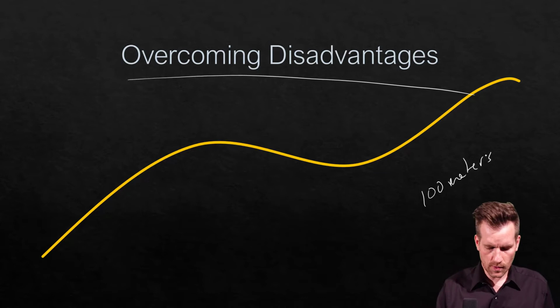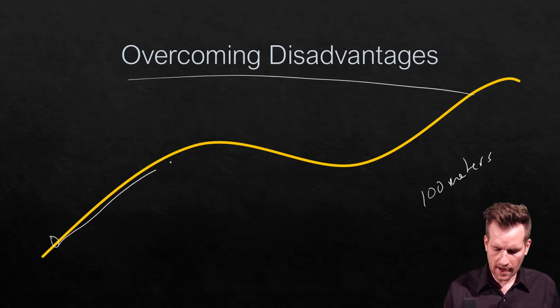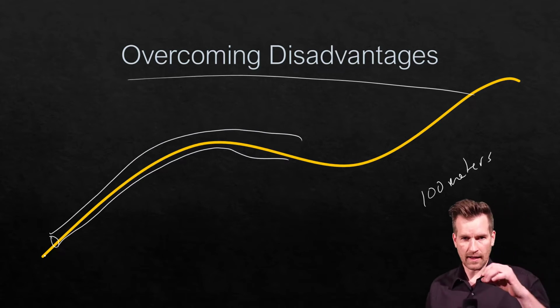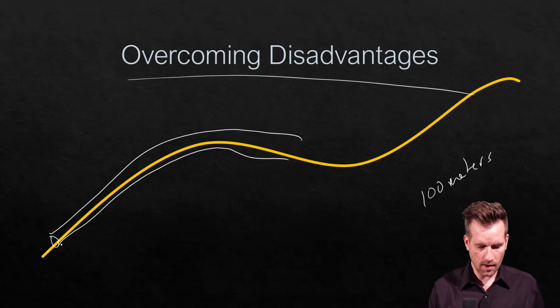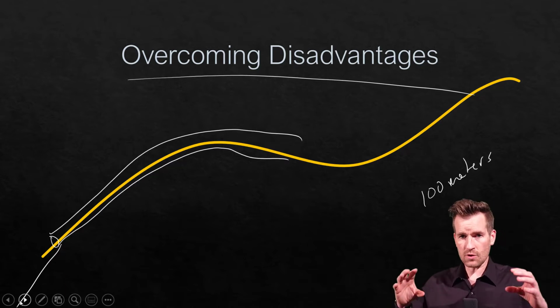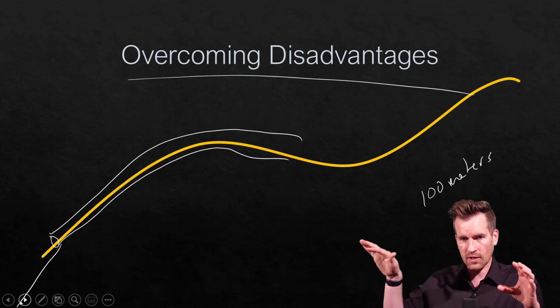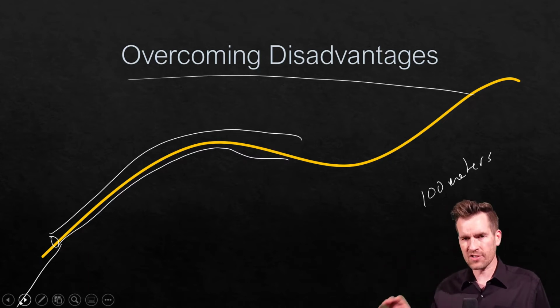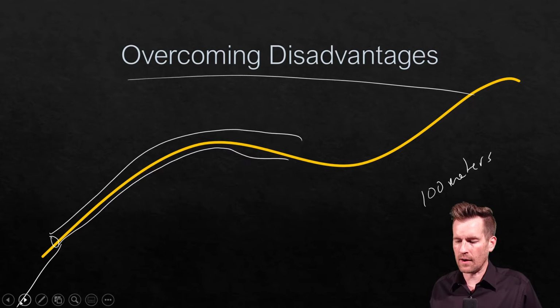Another thing that we could do is create a shielding around this cable. If we have a shielding, some sort of conductor that goes around it, and we ground that out, we put that to ground, then we can shield this data, or the electrons that are going through this, from outside interference. So putting shielding around these cables is one way that we can reduce the effects of EMI.